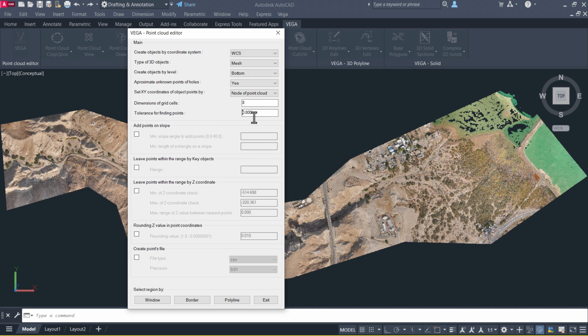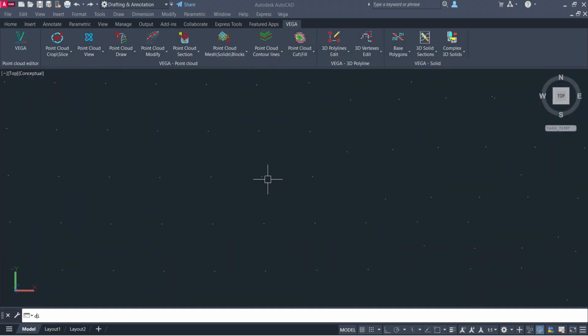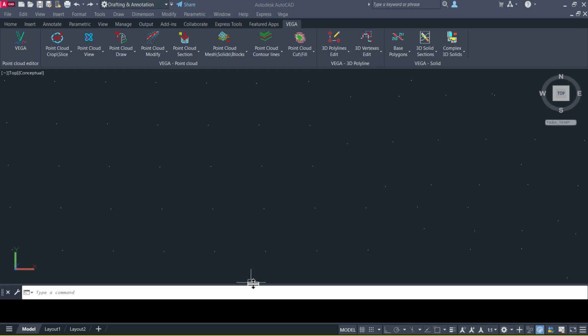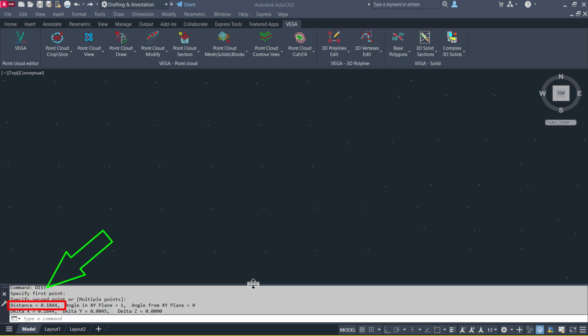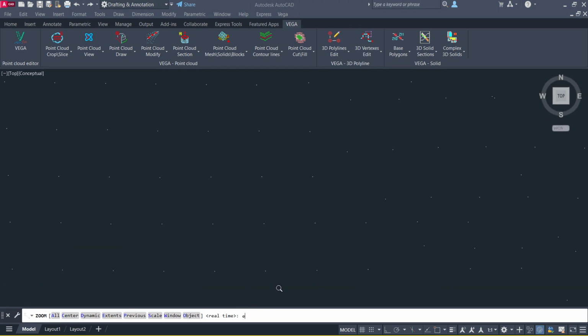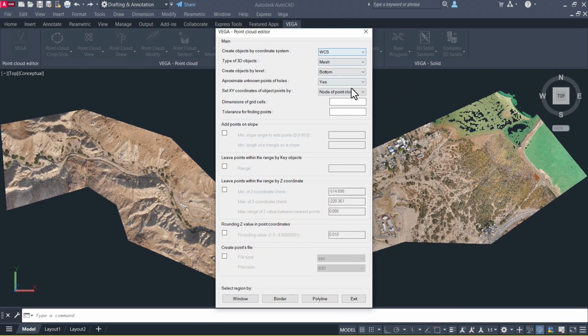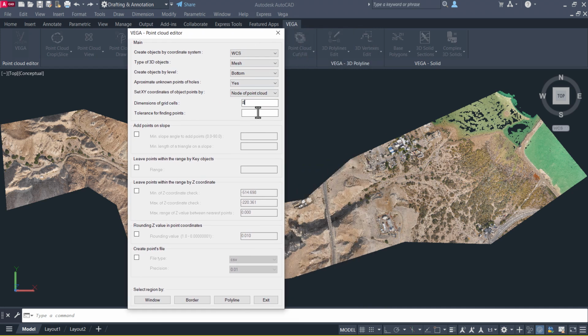Let's see what that is, and then go back to the parameters. The distance between its points is about 0.2. There is no reason to make it less than 0.2, because the points just won't be found. Let's go back to our command. Here we have not changed anything. The distance between the points is 8, which is the maximum on flat surfaces. Tolerance of 0.8.